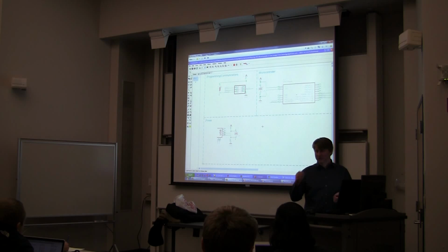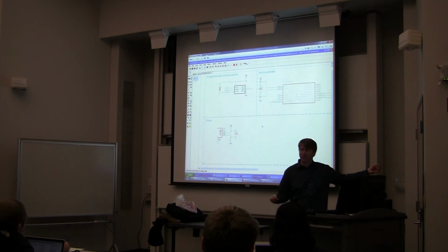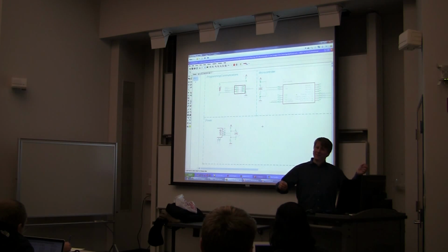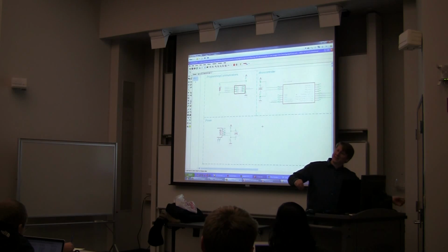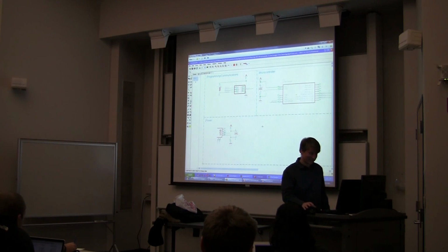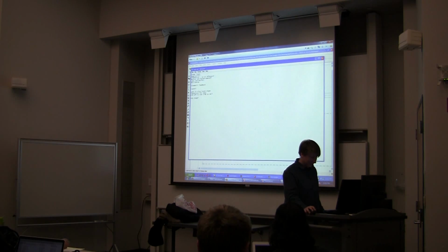It prevents random fluctuations because you're right, we're going to have a 6-foot wire. You know, when the microcontroller wants to do something, 5 volts is coming from way down that wire. You want things to not brown out and reboot every time you blink your LEDs. That would be bad. Okay, so let's look at my to-do list.